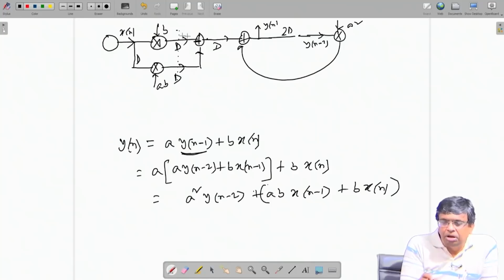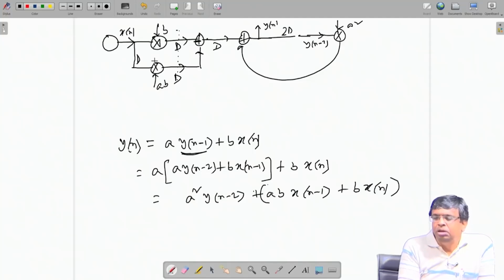Okay. So, the upper half or lower half, if you go up to this, the multiplier and adder, they are not coming in the same cycle, separated by delay, here also separated by delay. So, T m and T a, we have to take the larger of T m and T a, which is T m. Then again I cannot go further, there is a delay, they are not coming in the same time. Now, comes here, here I have got T m plus T a. Here nothing, because after that there is a delay 2 d. Earlier I had 1 d, but because of this trick, it has become 2 d.